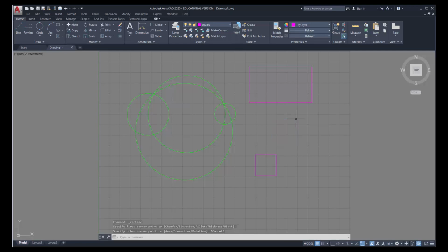Let me show you what I mean. Let's say I want to draw another square on top of this. I'm going to use the same tool. And if I find this intersection, well, actually I'm finding an endpoint. Remember, when lines are drawn continuous, it tends to select endpoints, even though it is an intersection by definition. Endpoint meets its criteria for selection. So I'm going to click on that endpoint. And now I can also do another one, a 1, 1 square. And one fits on top of the other.